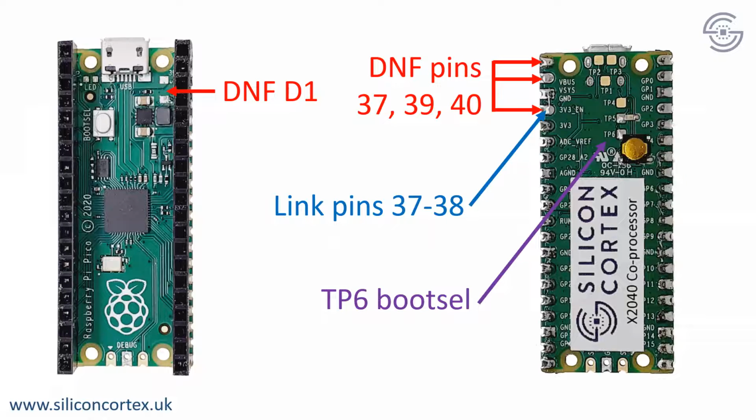Good. Right. So the question is, I was asked last time very quickly, I think it was by Jason on the call here, how can you connect a second Raspberry Pi Pico? Can I just stick it upside down and solder them all together and life is good? The answer to that is no, you can't. I've had a look at it. You need to do a small number of modifications. And let me just show you what those modifications are.